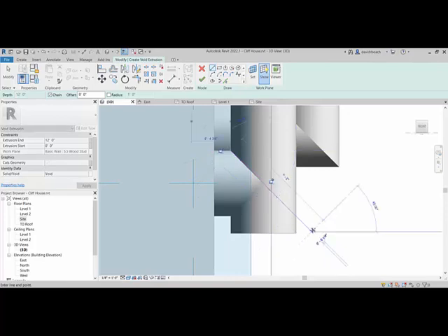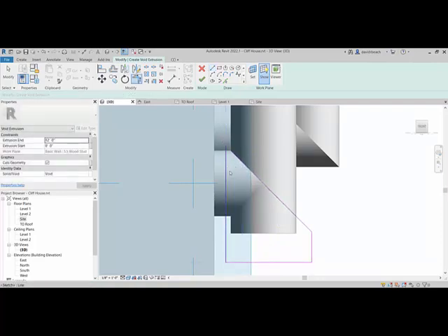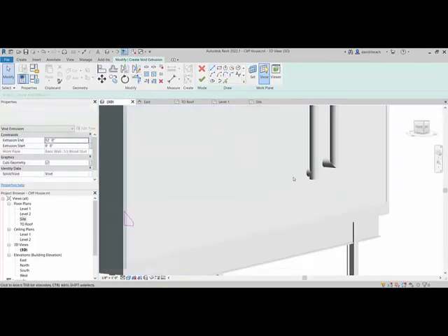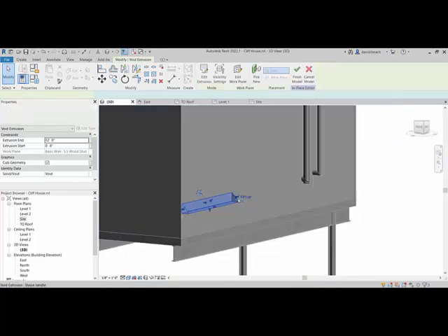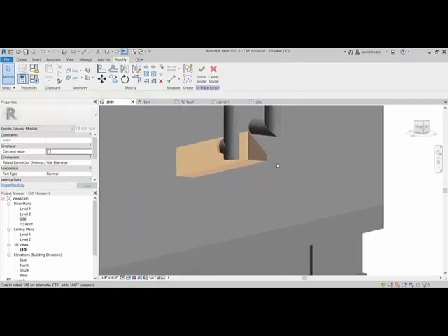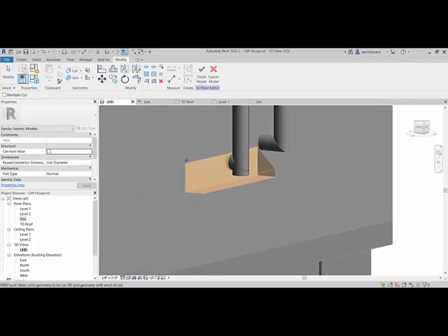Here to here, but this time I need that triangle going in the other direction. And cut. This cuts the vertical, and it puts them together perfectly. It was way too much work to get there. I would use the sweep. But there's almost always 2 options to do that.